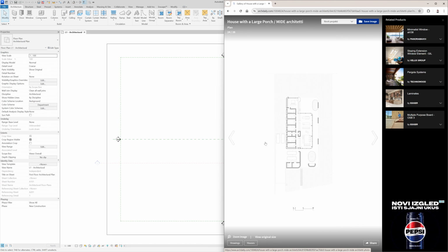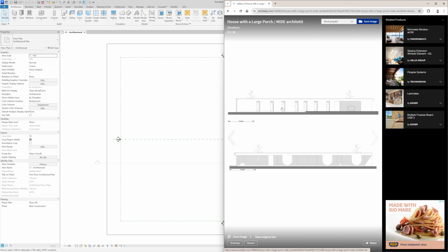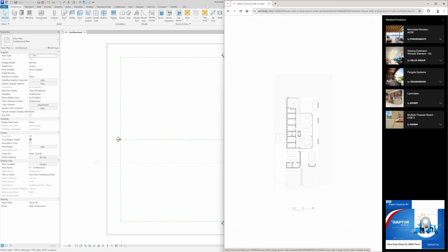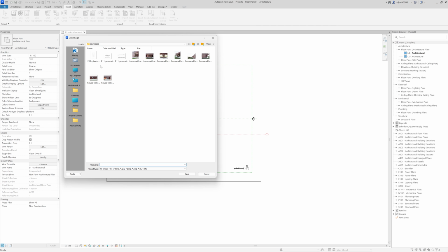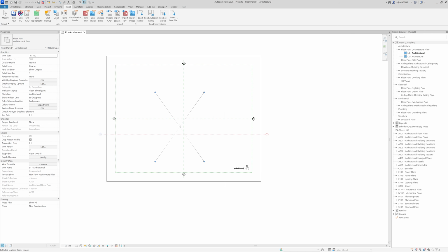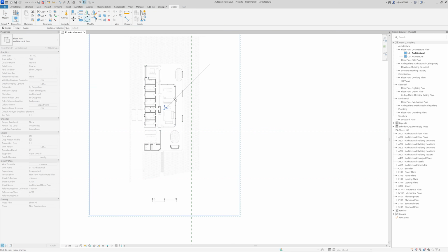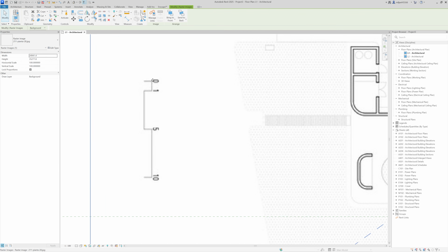What I would like to know is where is the north, so there is no north pillar here on a floor plan. And if we go to the facades, we see that this is the north facade and this is the south facade. So I'm going to place this floor plan, actually this image, in our plan view. And for that you go to Insert and then Link Image. So here it comes. And because I said that this is south, I'm just going to rotate this for 90 degrees. And then I'm going to scale this.